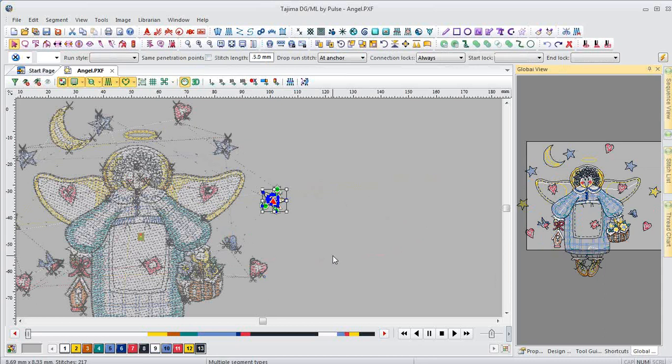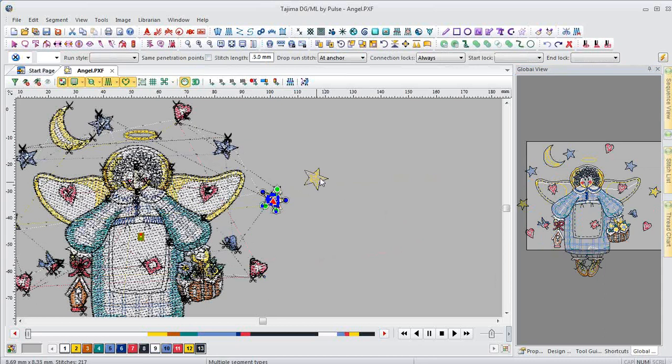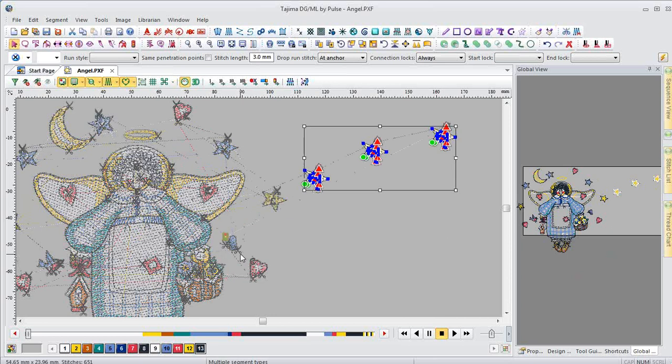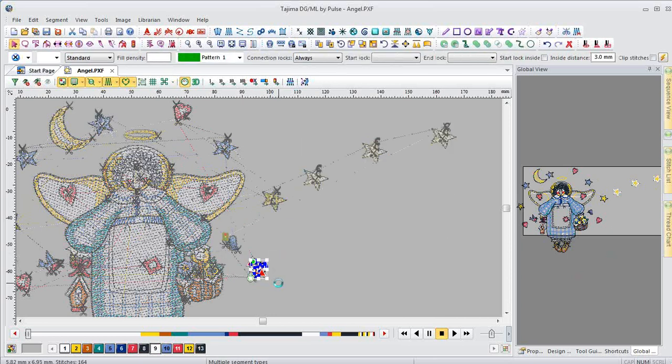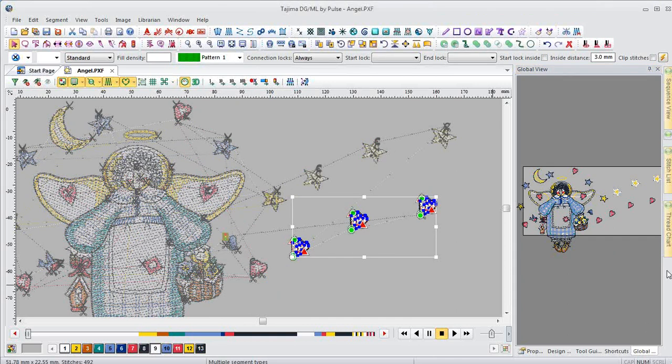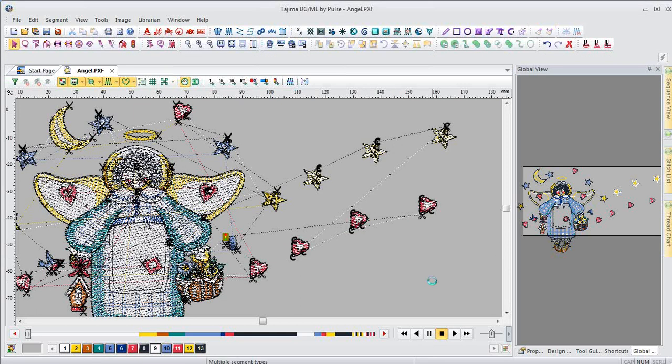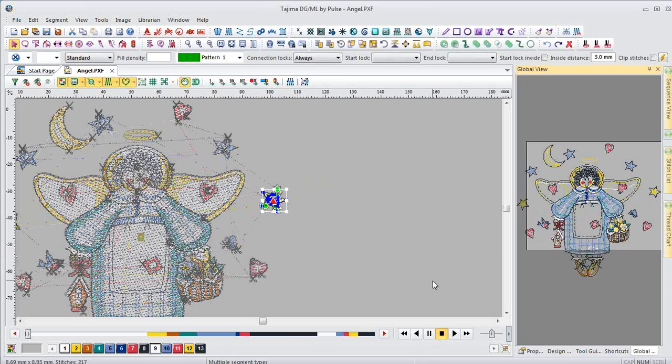Small features, very interesting. For example, duplicate. Okay, let's duplicate. Let's select the segment again. Shift L will repeat my last function. Now let's continue and let's see where else I can apply the repeat last function.